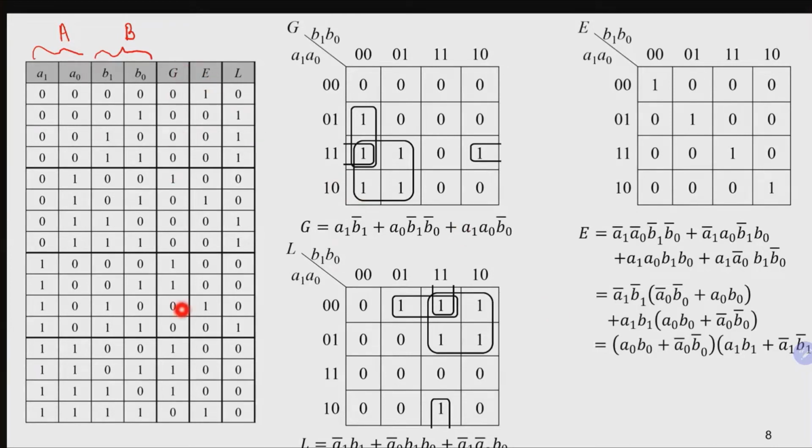For easier viewing, I split my truth table into groups of 4 bits, and then I can easily fill in my K-map. Okay, so first 4 bits is all 0, which means that this top row here is all 0. Second 4 bits, we go 1, 0, 0, 0. So you go 1, 0, 0, 0.